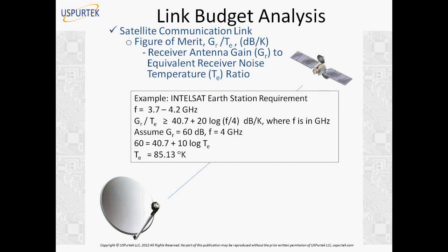Otherwise, your signal will be lost in deep space. You cannot simply make out signal from noise. For this reason, most of the commercial satellite links which are used for broadcast TV have low noise amplifiers, or LNBs, installed at the receiving antenna, right? That helps to overcome the noise level. And the primary reason for that is because the signal level is so weak because of the distance that it's almost indistinguishable from noise, and you must have a front end low noise amplifier.